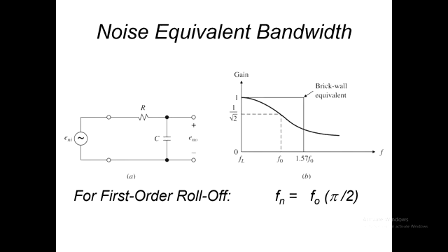We can't use the same index that we do for sine waves. When we have sine waves, we have this very kind scenario where in the transfer function of this first order system, when the real part and the imaginary part of the denominator are equal, then the magnitude is the square root of real part squared plus imaginary part squared, and that's where this 1 on root 2 comes from, right?